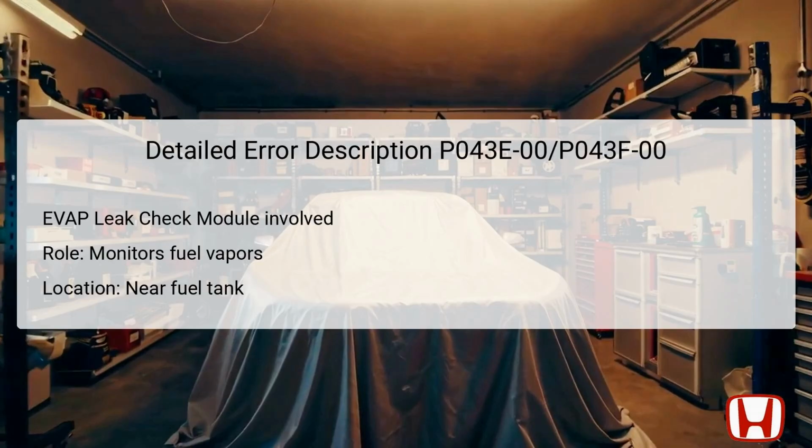optimally. The Evaporative Emission (EVAP) leak check module is integral to the functioning of the EVAP system, designed to monitor any leaks in the fuel vapor circuit, which is critical for reducing emissions. This module ensures that fuel vapors are contained and not released into the atmosphere. Located near the fuel tank, it interacts with various sensors and systems to evaluate pressure levels. When the PCM detects an anomaly in this pressure, it triggers the specific DTC codes.